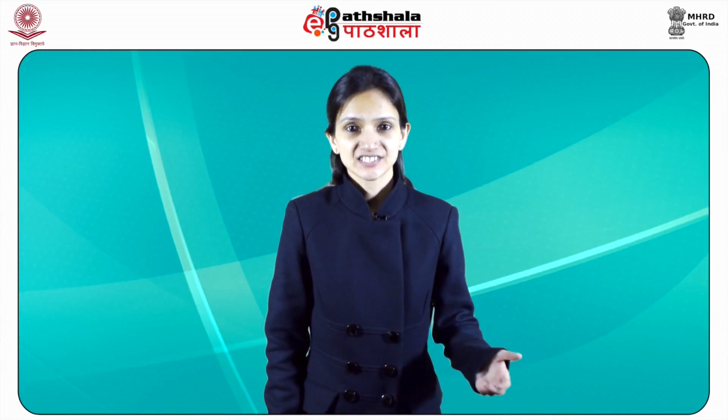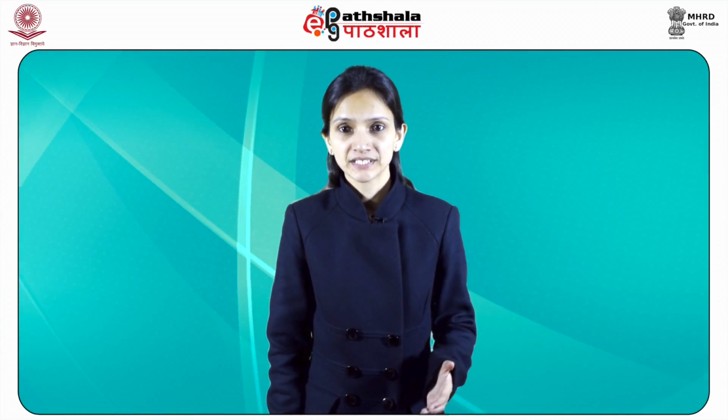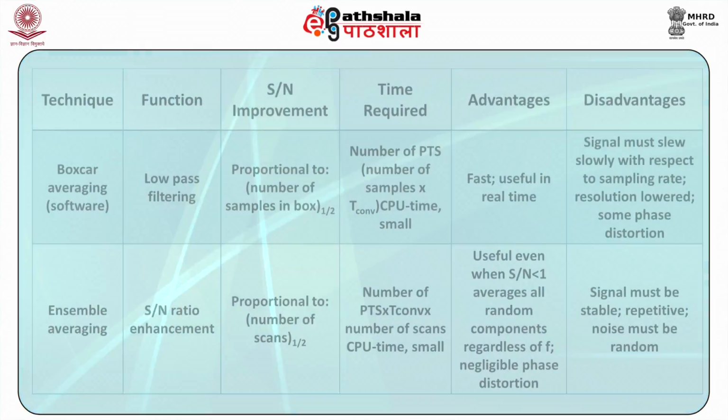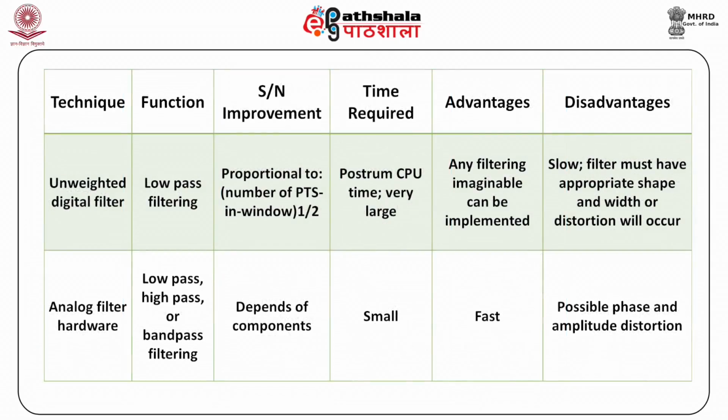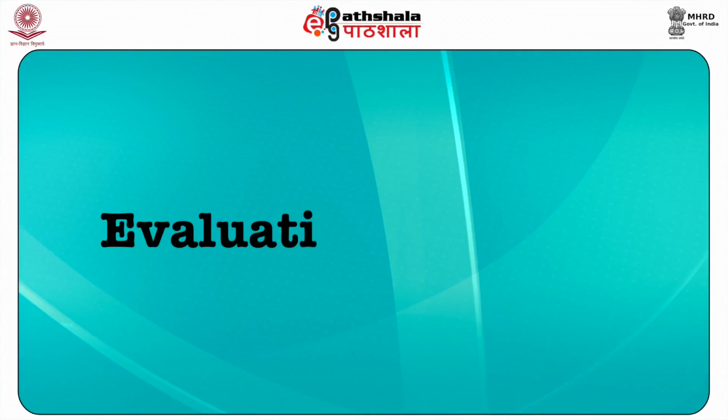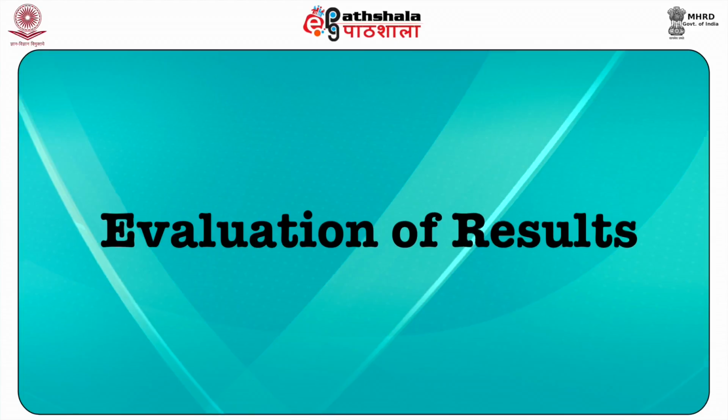Next is data treatment by filtering, smoothing, and averaging. We can see in the table the technique, its function, S by N improvement, time required, advantages and disadvantages. The various techniques mentioned are boxcar averaging, which is software; ensemble averaging; unweighted digital filter; and also analog filter hardware.